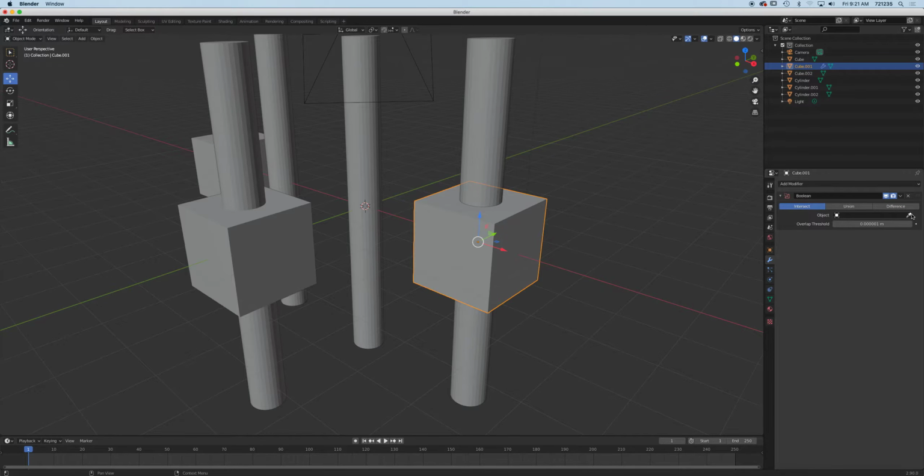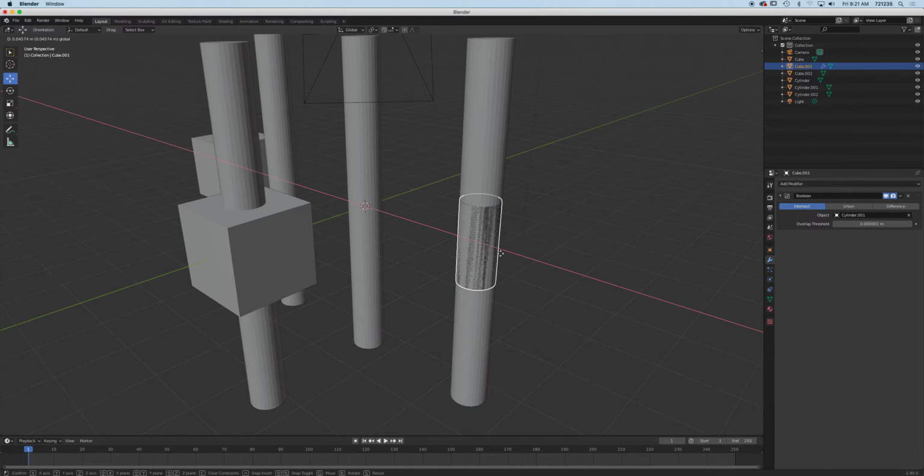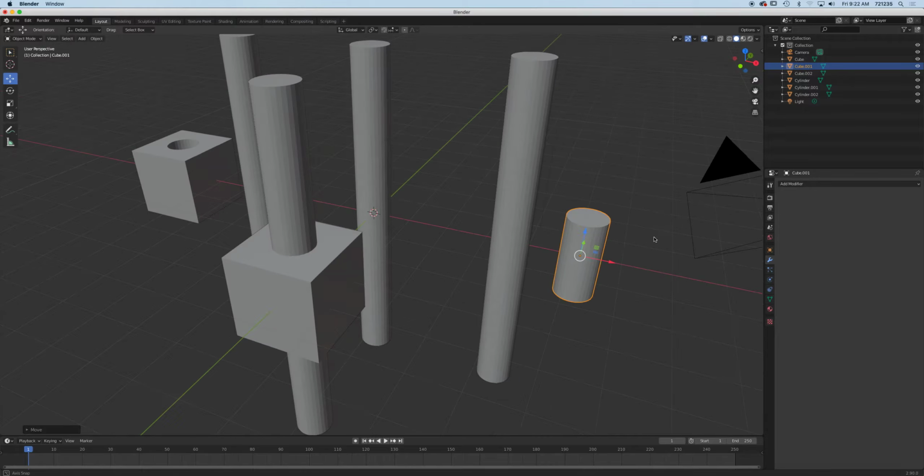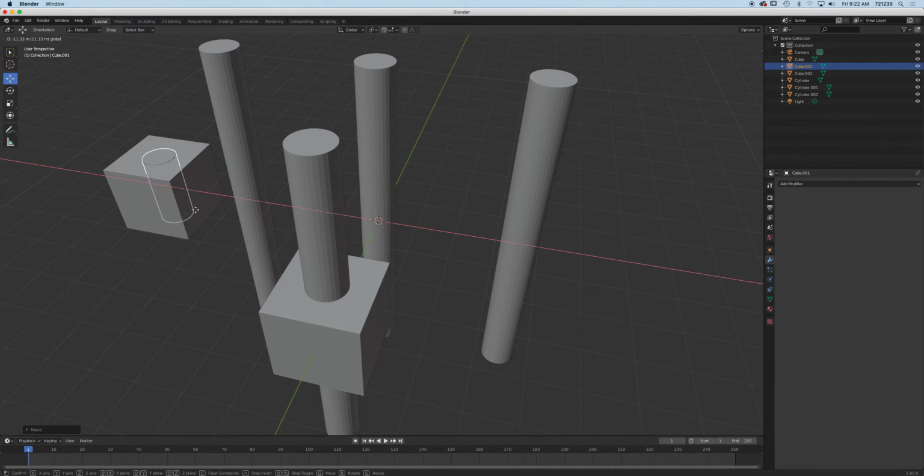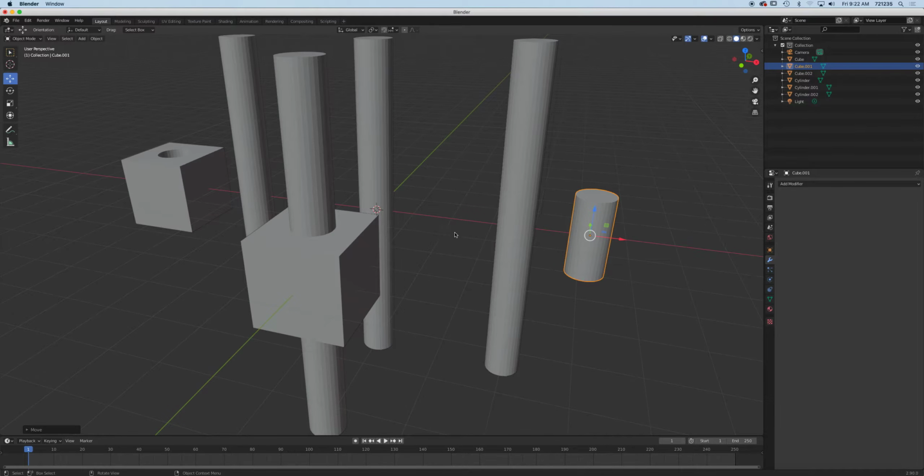Okay, we're going to eyedrop what shape we want to intersect. It's obviously you already see it, and then you can move that about, if you want to reposition it. Then right here you're going to hit apply and then move it out, or move that there with precision. It would fit that one. All right, so that's Boolean operation. Let's put it into practical use.